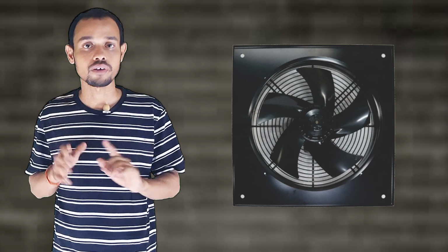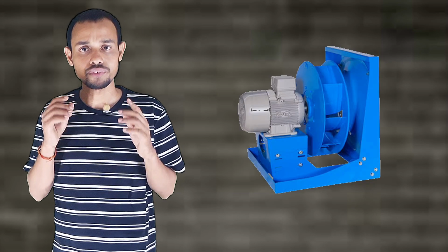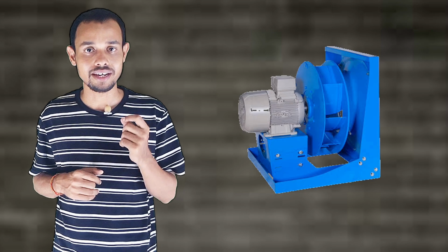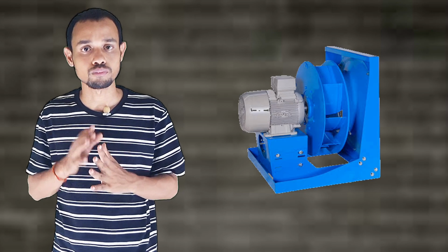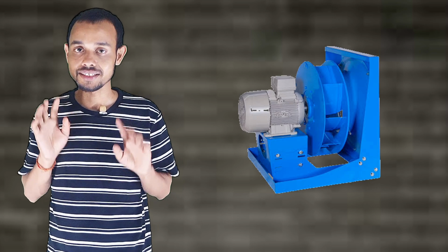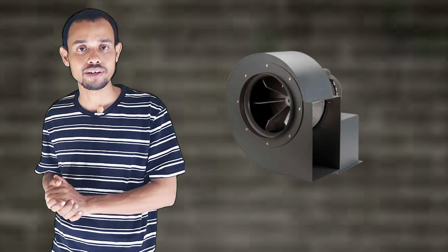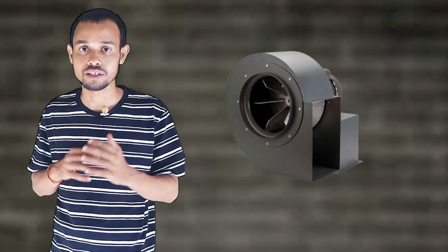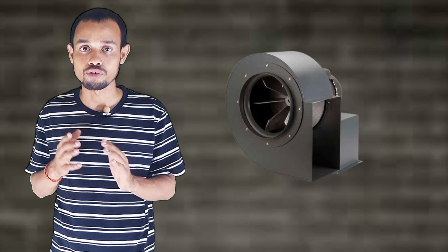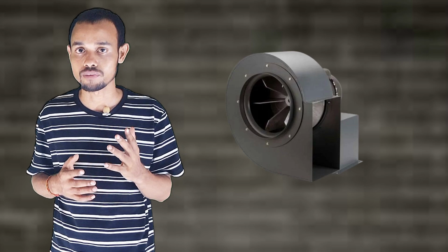And six is plug fan. Centrifugal fan without a scroll housing, mostly used in the air handling units, flexible and compact design, used in modular HVAC, pharmaceutical ventilations. Okay, and seventh is a radial fan. What is radial fan? For the high pressure applications, very strong and sturdy design, used in heavy duty environments, used in the fume systems, paint booths.